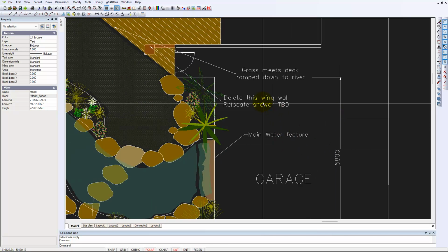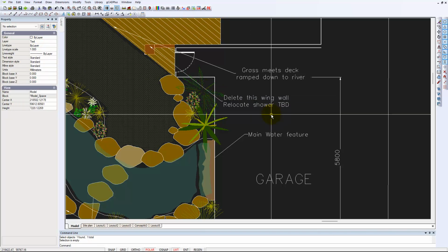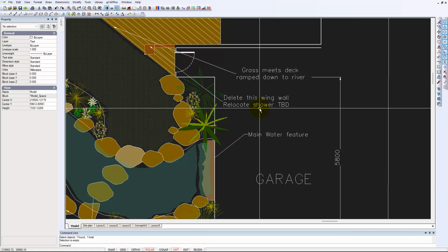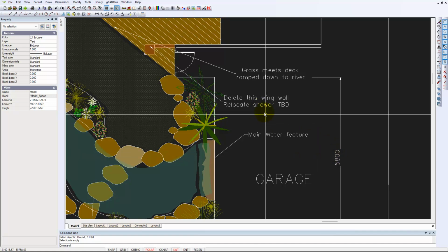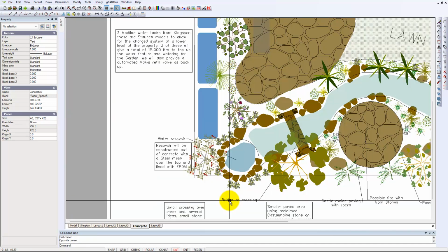But unfortunately, because other text is also on that layer called text, these are indicated there, they are leaders. We change the text height here, we'll change it there. So you might want to separate out dimension styles and other labeling text, and be just careful that if you change one thing, it can have a cascading effect. So I hope that helps. Just look at this drawing, slightly improve it, and get a much better result.